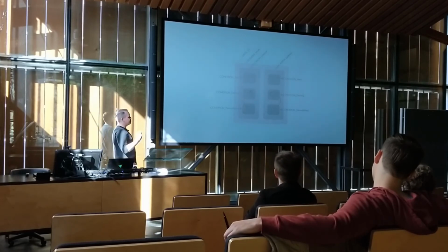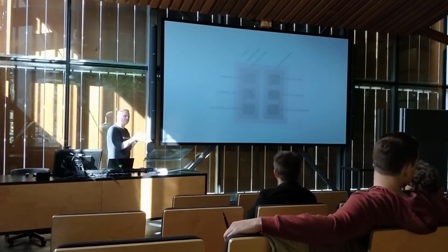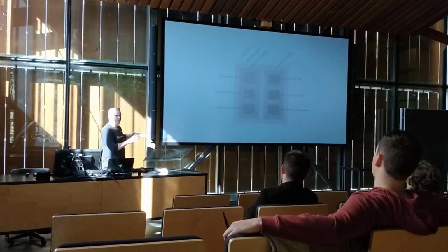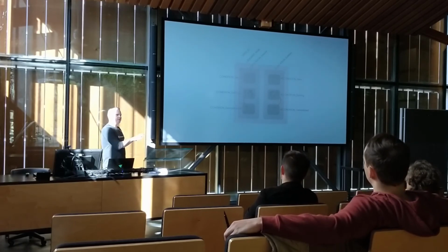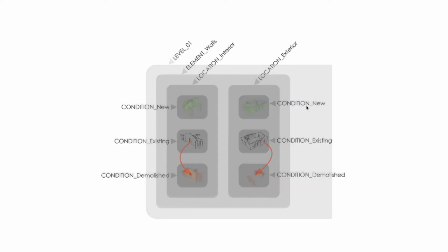The other tip, when you're moving into this phase, is that you save your existing conditions model, and then you save as, and you call it proposed conditions. So now you have this record of your existing conditions as it was when you finished, and you can always go back and get what you need out of there. And it's easy to paste in place between models. All right, and then when you start developing new ideas, you add those to the new level of model organization. So you start building your new walls and call those new.